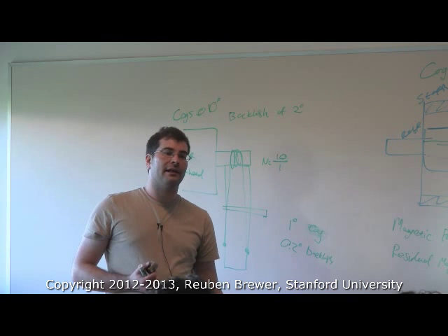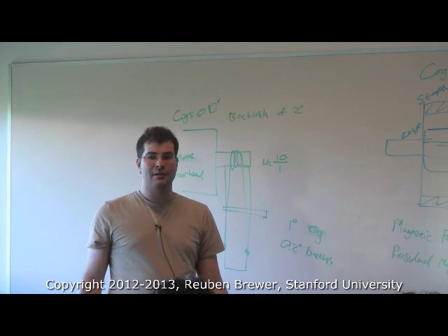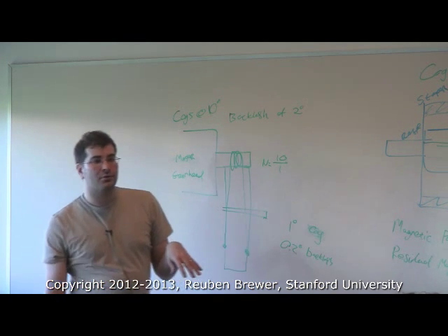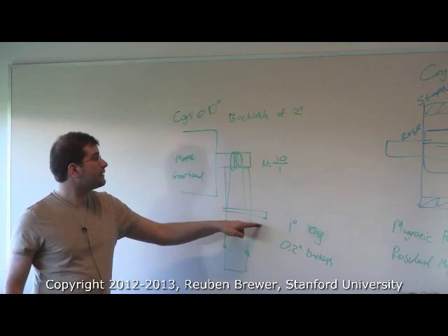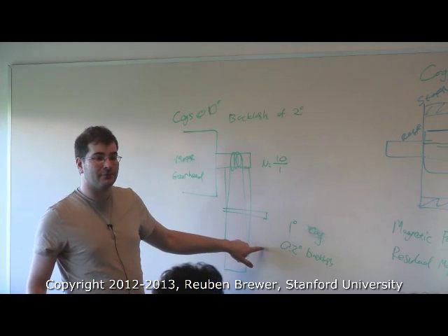You can't get rid of backlash. You can't get rid of cogging. Well, I mean, you could choose a different motor or a different gearbox, but you're still going to have some badness at some point. What's important to know, A, you can't get rid of it, but B, how you mitigate it. So I can reduce my cogging and my backlash by throwing a cable transmission on.